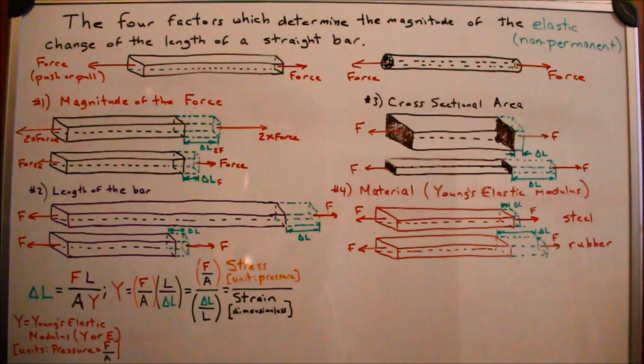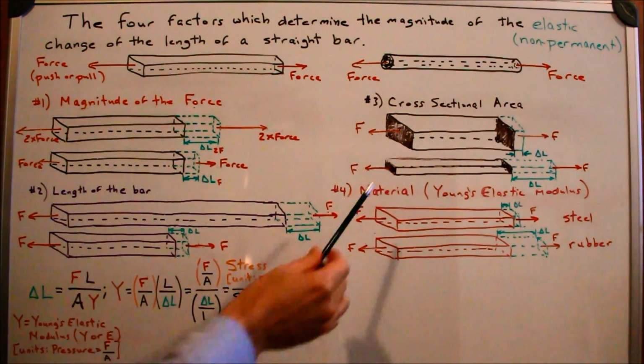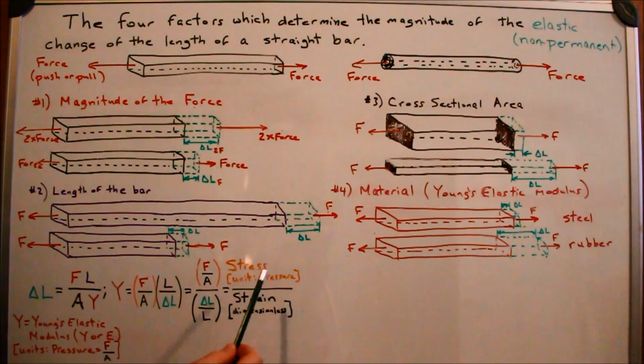So I put stress on a part, I put so much force on it over area, that's stress, which has units of pressure, and there's a resulting strain which comes from it. So the strain is the change in length over its length. So that's a dimensionless one. So Young's modulus defines, when I put a stress on something, a force over an area, the higher the force and the less area, the more stress I put on it. There's a strain that comes up, and this relates those two.